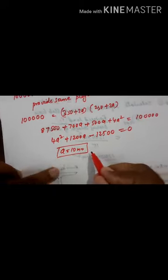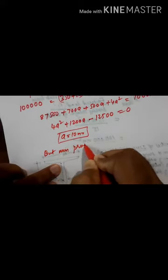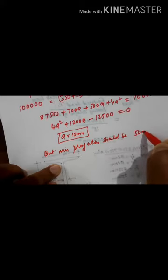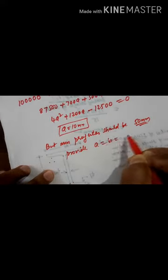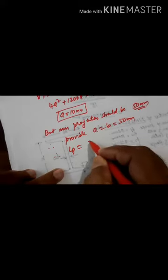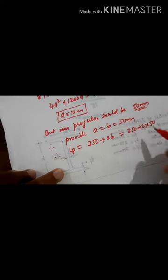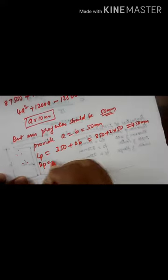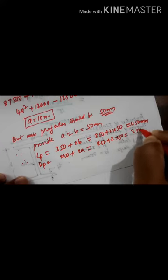But the code says the minimum projection should be 50 mm. Therefore provide A equal to B equal to 50 mm. Now I can write LP will be 350 plus 2B, that is 350 plus 2 into 50, you will get 450 millimeter, and width of the plate will be 250 plus 2A, that is 250 plus 2 into 50, you will get 350 millimeter.